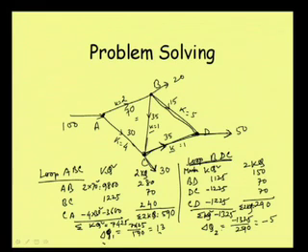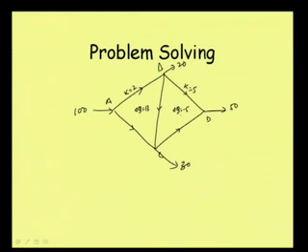Now if we apply this correction, how will this flow change? Well, now we are getting the values of delta Q1 and delta Q2. Let us see how we can apply this correction to our earlier loop. Here we are putting delta Q equal to 13. So plus 13 means that we will have to deduct from the clockwise flow, and minus 5 means that we will have to add to the clockwise flow, and just the reverse things we will have to do here.